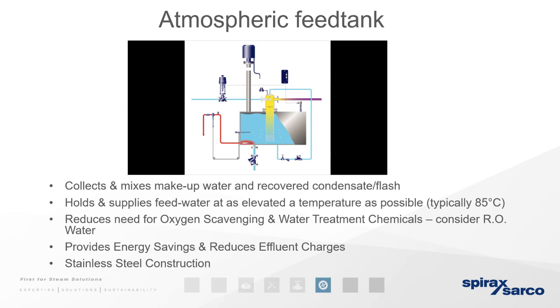First and foremost, less energy is required to raise the steam than from a lower temperature. We just saw that from the steam tables. At 419 kilojoules, we raised it from 0 to 100 degrees Celsius. And if we go up to 10 bar, which is 185 degrees Celsius, we would require 781 kilojoules per kilogram. So if we can have a much higher temperature in our feed tank, it would mean that we would require less energy to get that water to its boiling point, therefore saving money.